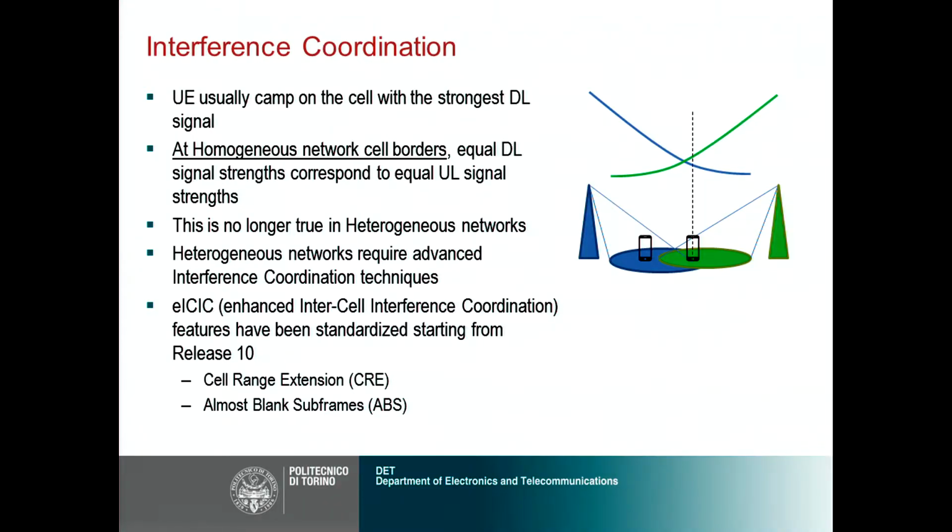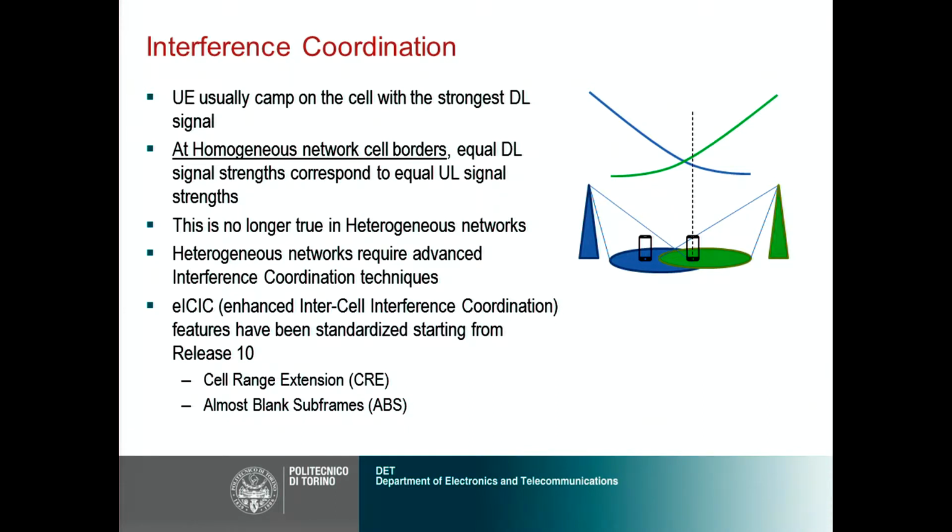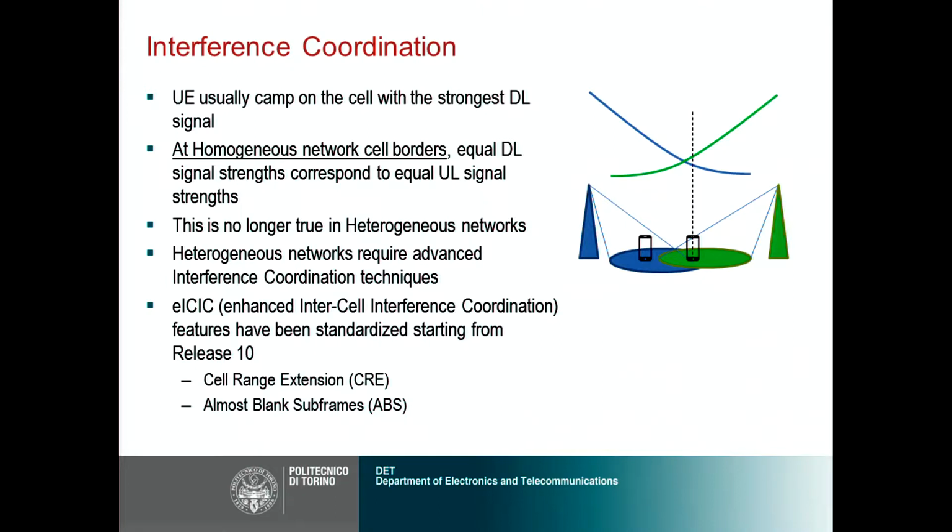But anyway, this is something that has been known by operators, and what operators do is every time you associate to a cell, they have a sort of hysteresis that prevents going back to the previous cell unless the margin between the two received powers is higher than a threshold.